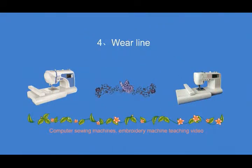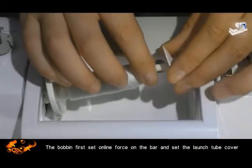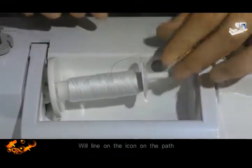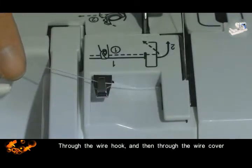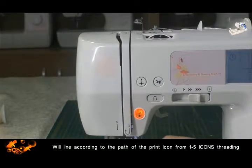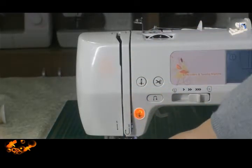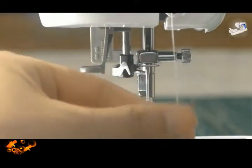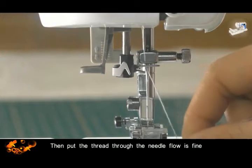4. Threading. First set the thread on the rod and set the thread cylinder cover. Lead the thread along the path on the icon, through the wire hook, and then through the wire cover. Thread according to the path of the printed icons from 1 to 5. Bypass the take up.